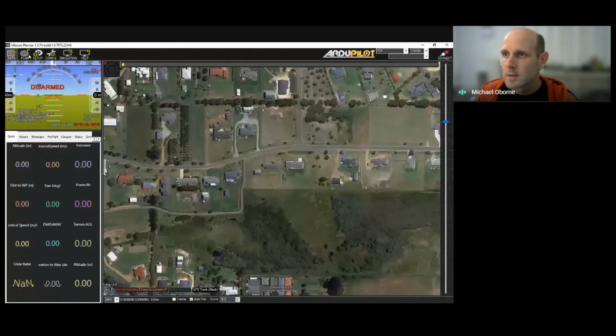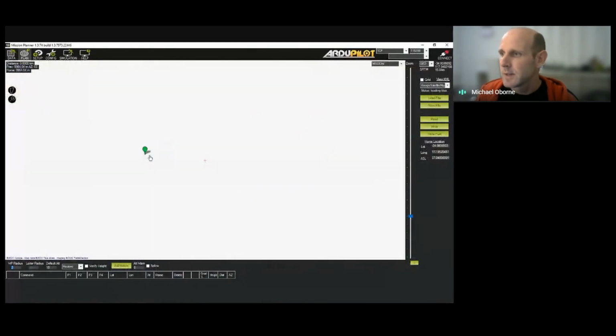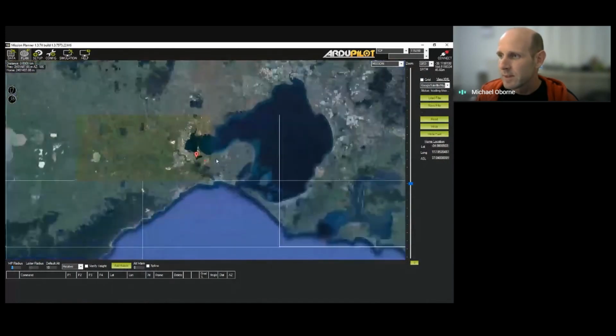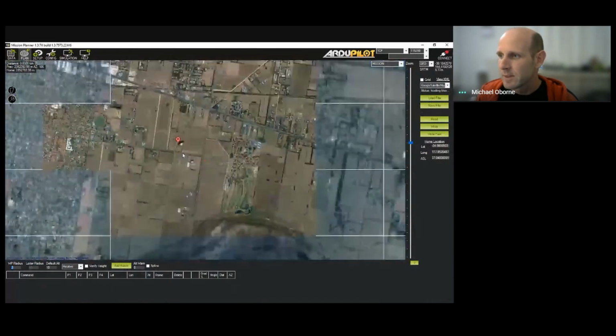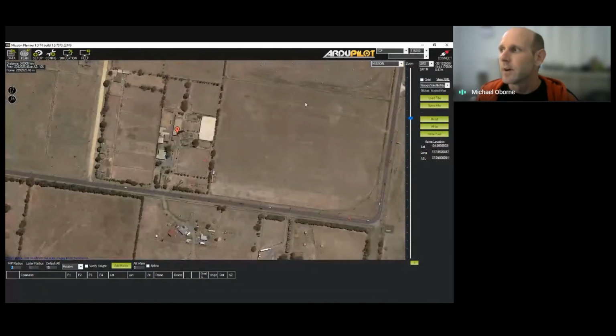Because I know where those points actually are, I'm going to zoom out, and where those photos were actually taken. Okay, so as you see at the moment, it's the original photo, just a Google Earth photo. And if you actually look, you've got our lat, long, and altitude. So our altitude is currently SRTM. As I move my mouse around, you can see it's SRTM.